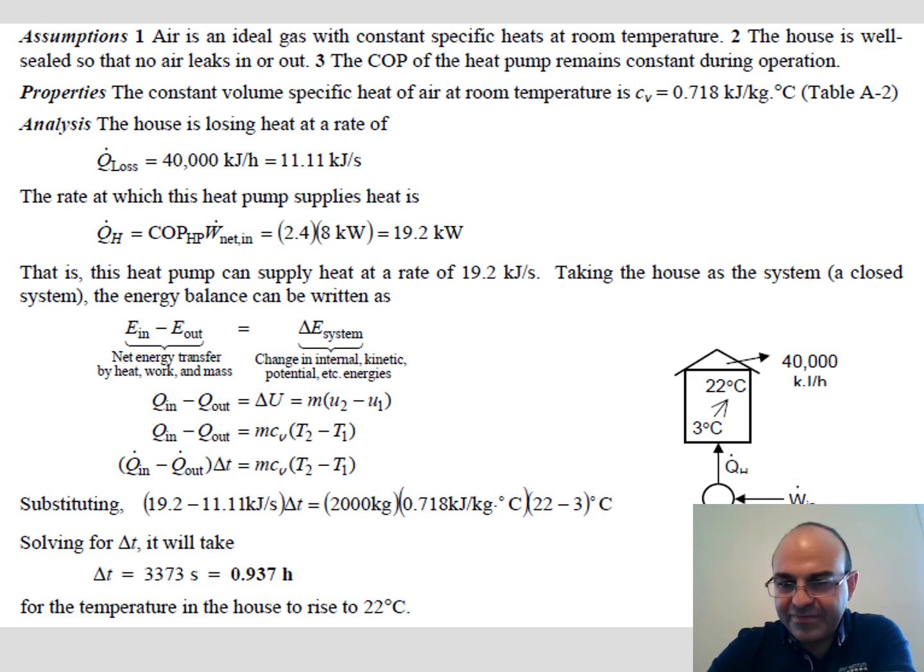Okay, we sort of have the schematic here. So we do have a heat pump at the bottom. So QL, which is covered here, is extracted from the surrounding. And then the compressor work is used to transfer this QL from the surrounding. So QL plus W dot of the compressor becomes Q dot H, which is provided to the house.